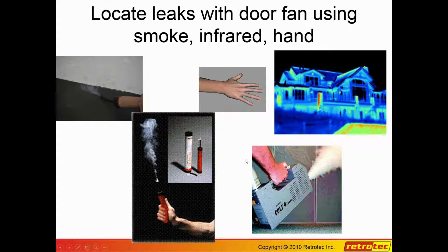Now here we show someone using a theatrical fogger, which I don't think has as much application in super tight houses as it will in real leaky houses. It's based on a heated oil, and there is a little bit of oil that condenses out from this. It is a safer smoke. It's the same smoke that they have at rock concerts and so on, or plays or theater and so forth.